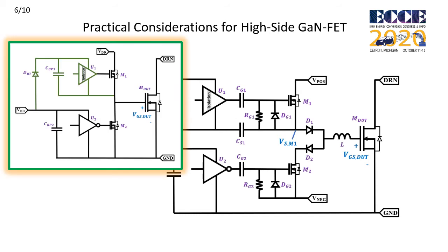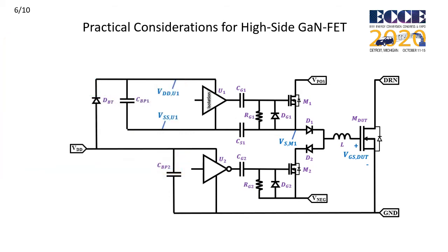If we take a quick look at the conventional half bridge once more, you can see that all expended charge from M1 is ejected into the primary power flow path. Now in this case, this has been made impossible by the introduction of CS1, and as such we need an alternative path for the charge to be released. And so we add one small additional transistor, M3, whose job it is to periodically release this charge to ground.